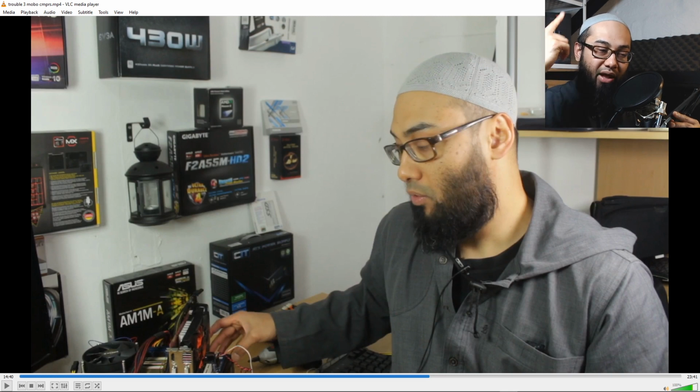There is one kind of test you can do, which some people do, and that, again, in the video we mentioned, is you get what's called a motherboard tester. It usually comes in the form of a little PCI card, and it has a little LCD display. You plug it into one of the PCI slots, and it should give you some codes to signify that the motherboard has a specific XYZ fault.